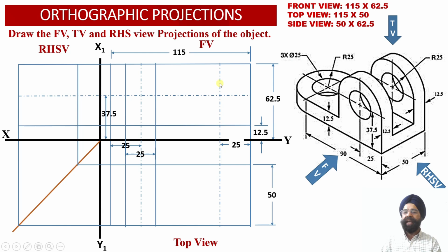So these two center lines, wherever they intersect with each other, we are going to obtain the center point corresponding to the circular hole over here into the two vertical webs. Since this object happens to be symmetrical, as the observer looks at this object from the front view, the circular hole in the front side vertical web and the circular hole in the rear side vertical web are going to overlap with each other.